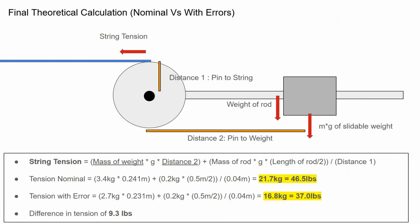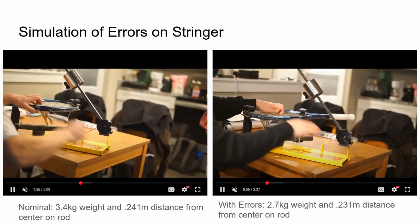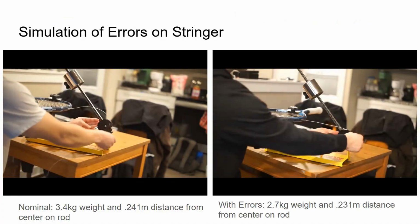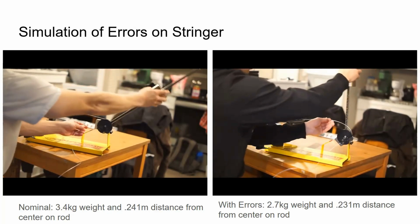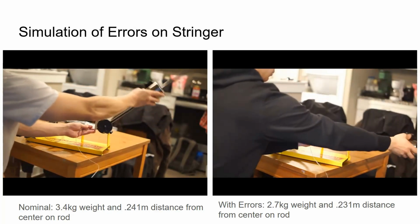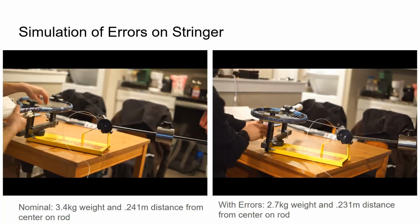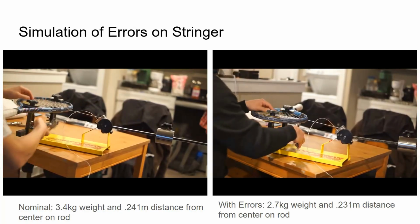Calculating the tension with the thermal, encoder, and cosine error, we get 37 pounds, creating a difference in tension of 9.3. We can verify our calculations by applying the error values on our actual stringer. So first, I strung the racket with the nominal values, 3.4 kilogram weight and 0.241 distance from the center. Next, I used the values with the errors, which equals 2.7 kilogram weight and 0.231 meters distance from the center.